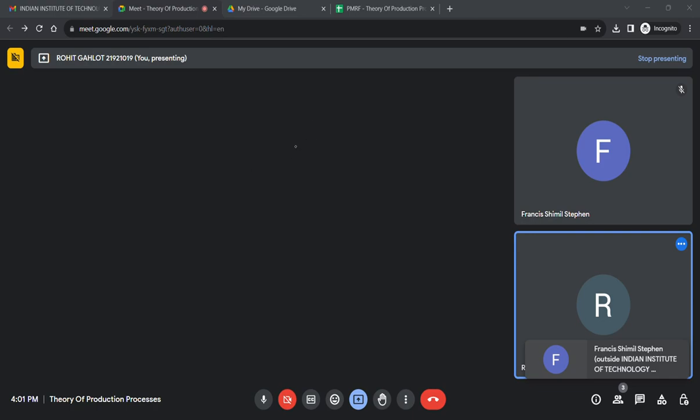If the question gives a side riser or a top riser, sometimes it is not mentioned, sometimes it is. Here it is mentioned that it is a side riser. For a side riser, we usually take h equal to d. I am not discussing the theory of why it is so; we are just here for solving the problem. So for a side riser, the height is generally taken as its diameter.